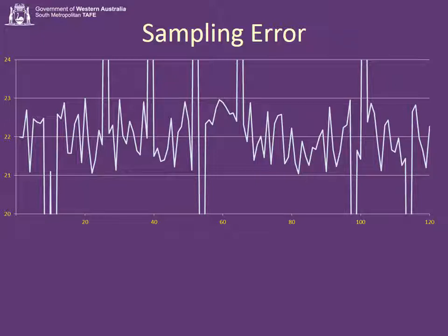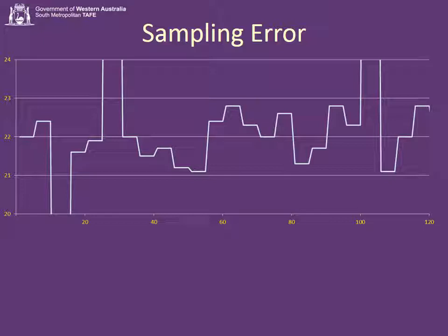Now, that could cause a problem if we read that in, because the control system might take it as a real reading. Now, first thing to do is remember that the ADC will only sample periodically. So the ADC sampled input, what the BMS system sees is actually this. Sod's law says that even though the flickering is only happening occasionally, we will occasionally sample it. So that's going to give us a bit of a problem because the BMS system is seeing the temperature suddenly leaping down to 10 degrees Celsius and then suddenly not long afterwards leaping up to 80 degrees Celsius.